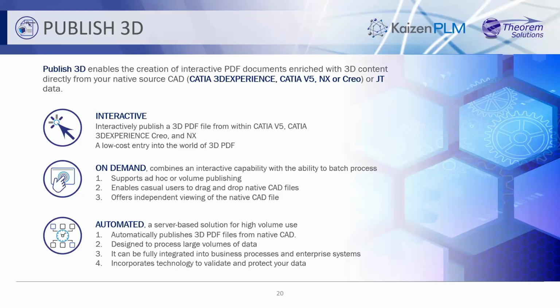An example of that is if you were a Teamcenter user, in the past, we've worked with a company to utilize 3D PDF utilizing Dispatcher from inside Teamcenter. Dispatcher has the ability to run an external process provided you can effectively run it programmatically. So Dispatcher can run our software, create the 3D PDF, and save that 3D PDF back into Teamcenter.